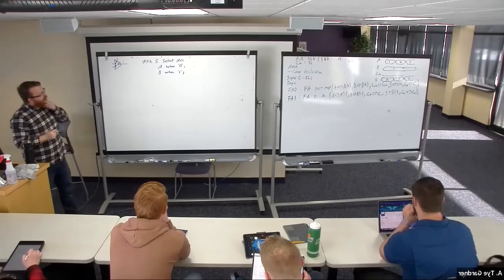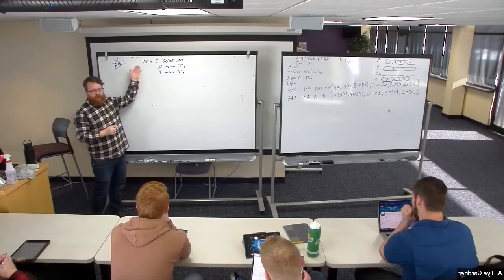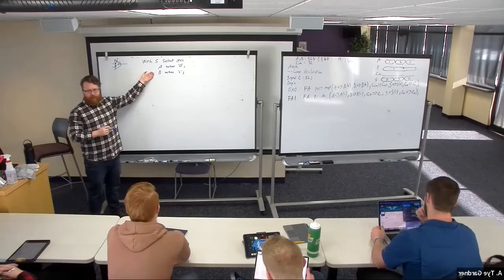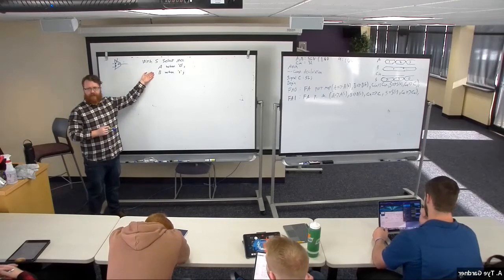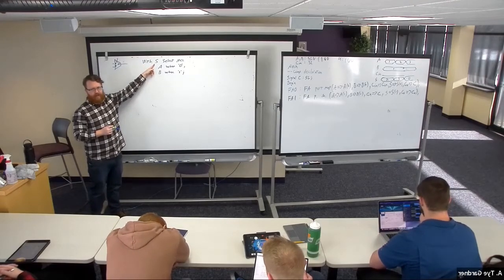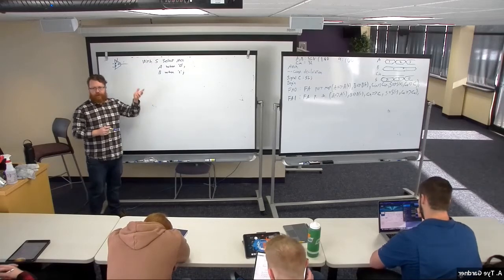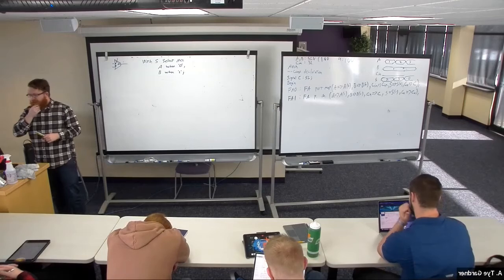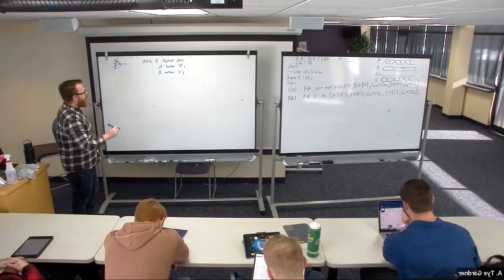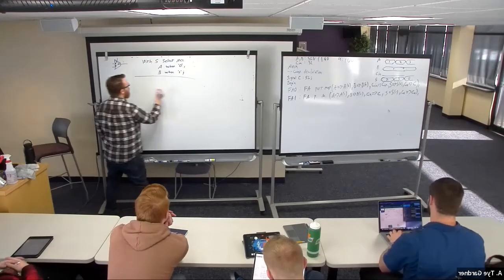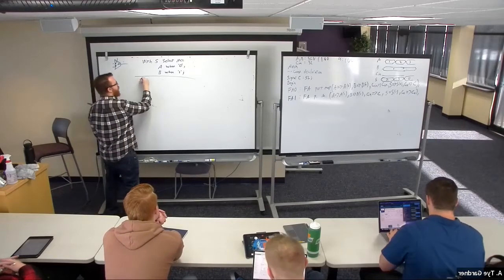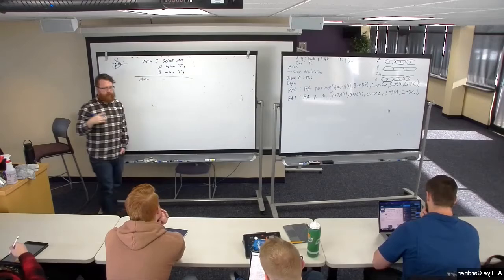However, this has a huge advantage over the 3 input truth table, which is if I want to build a 4 input mux, I don't have to go back to the truth table and write the logic. I just extend S to be a vector and I make it more rows. And I'm going to do that with something slightly different, which is the when-else statement, which is the easier way to do the same thing. So what a when-else says is, let's just go ahead and call M gets assigned to something when S.